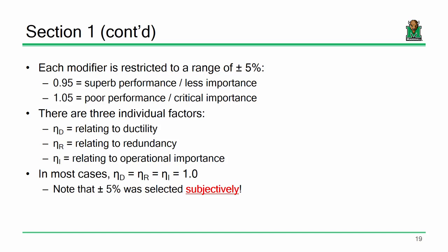You all remember from civil engineering materials or construction materials, you take a piece of steel or a piece of material, you yank on it, and initially it behaves elastically, but there is a point when you yield that material and then you get permanent deformations. That range of permanent deformations, how much permanent deformation it can withstand before it fails, is a simplistic way of expressing its ductility.